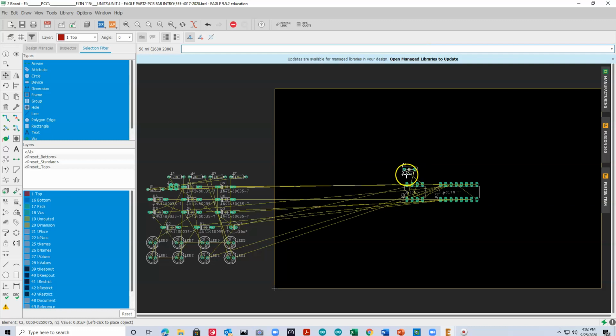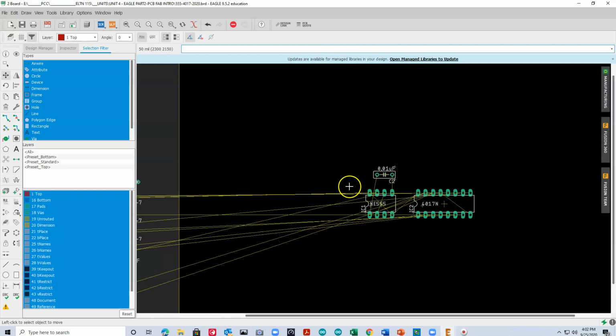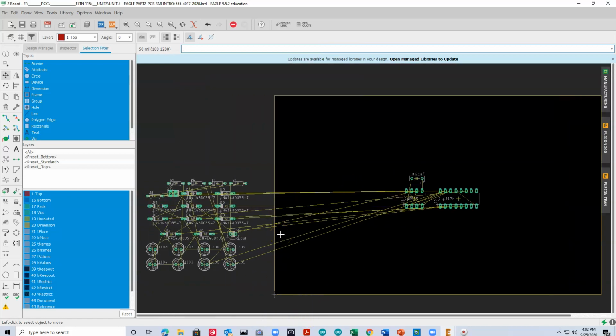I notice that this is rotated, and you'll notice that these two lines cross over. If I right-click twice, I get what looks like a more logical location for that capacitor. If you're missing that capacitor, don't worry. That one isn't really necessary for the circuit operation, but it shows up from time to time. Now, the next thing I'm going to add on here is C1, and the reason, again, is that it's got a connection point close to the 555 timer.